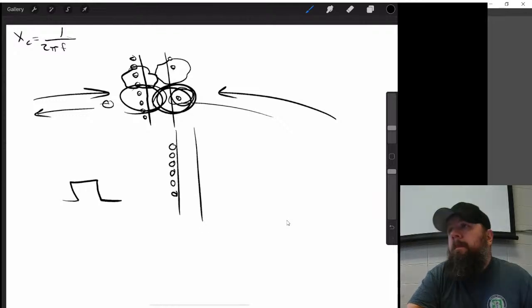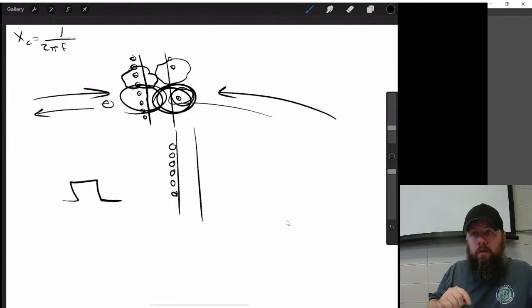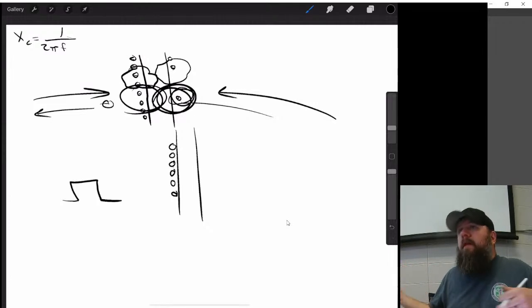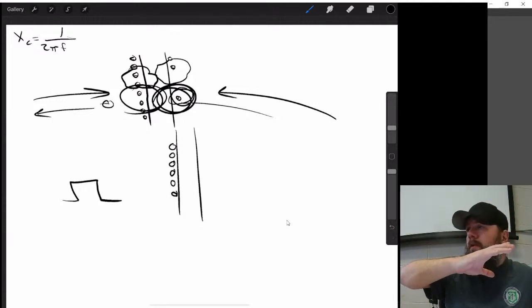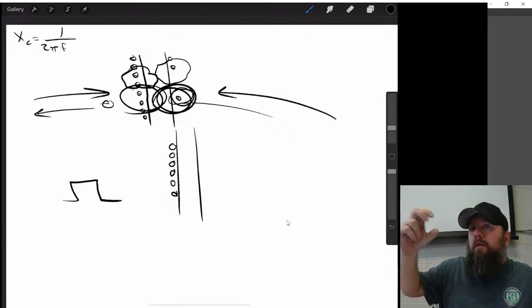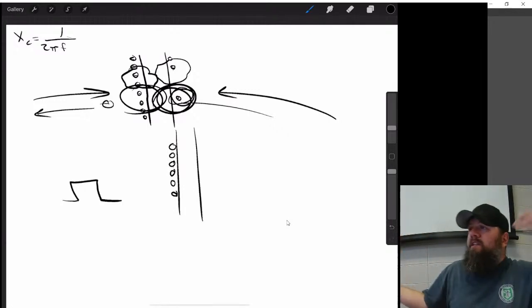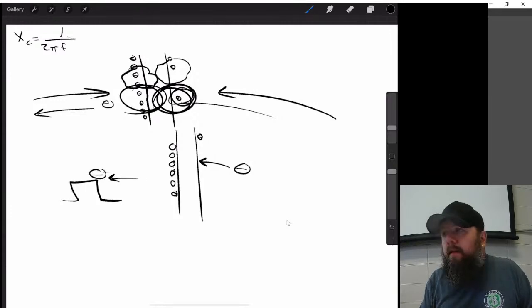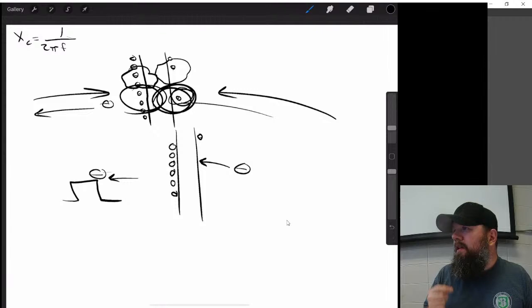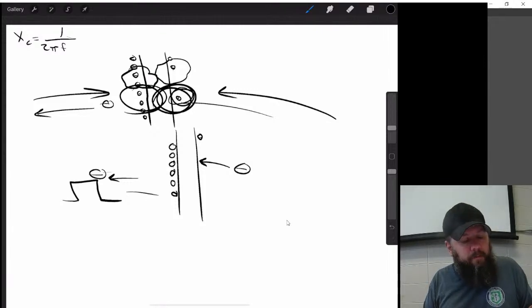And then if the frequency is slow enough, I'll charge up a plate and then it won't be able to go, right? And then whenever it changes direction, it'll start going again and then it'll fill up and it can't go anymore, right? So there's some amount of resistance there. But as I speed up, what happens? For every electron that I put in, I didn't fill up that plate yet. There's an electron coming out. And then I change direction before I completely deplete that other plate to start filling it back in again, right?